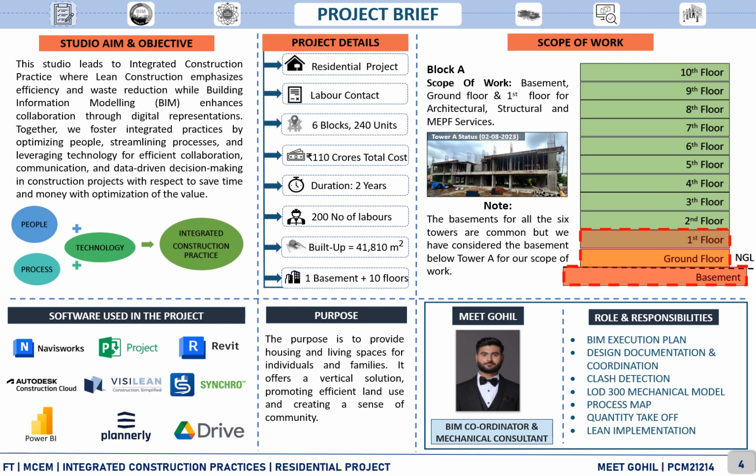I, as Meet Gohil, had taken up the role of BIM coordinator and mechanical consultant, undertaking the responsibilities of creating BIM execution plan, design documentation and collaboration, performing clash detection, creating mechanical model for level of detail 300, creating process maps, creating a quantity takeoff for the mechanical model, and the lean implementation.